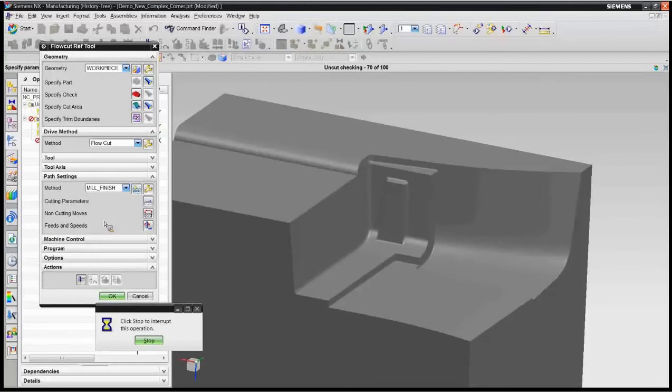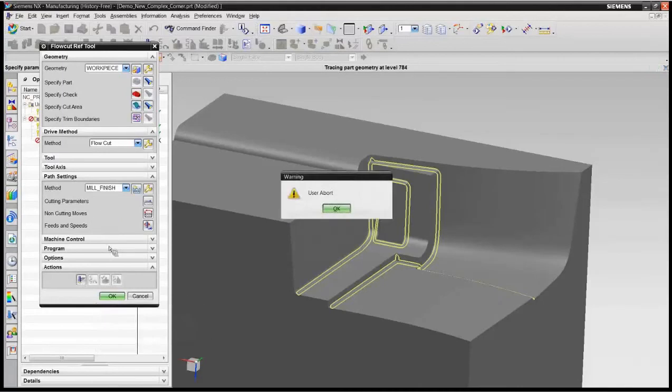Now we're coming in with this 2mm ball, and we're going to profile the corners. And we've got mixed operation type, tool path types, to where depending on whether it's steep or non-steep, we will get different directions of cut. And I'll show that here in just one moment once it finishes figuring it out. Figured something, I think, guys.